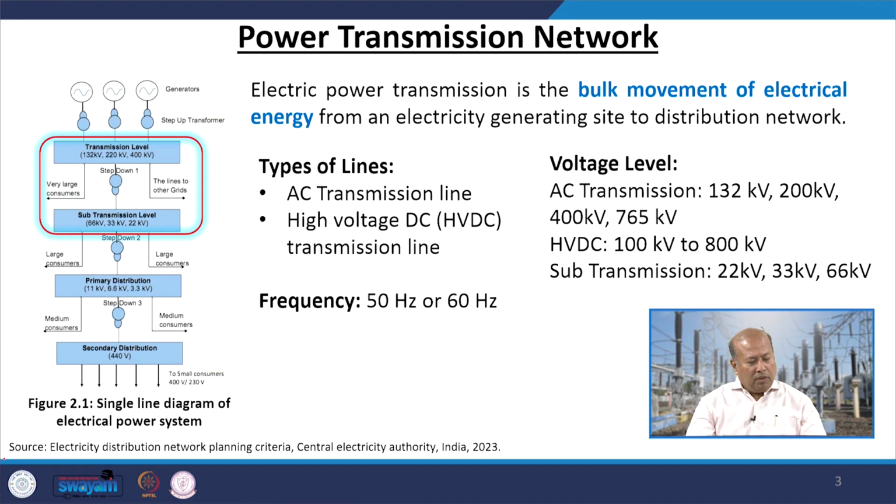Now, in our previous lecture, we focused on transmission and distribution levels. As you could see, based on the voltages, 400 kV, 220 kV, 132 kV, specific to high voltage operation of any grid is normally known as my transmission system. And then we do have a little bit lower voltage, that is 66 kV, 33 kV and 22 kV, which are considered to be sub-transmission level.